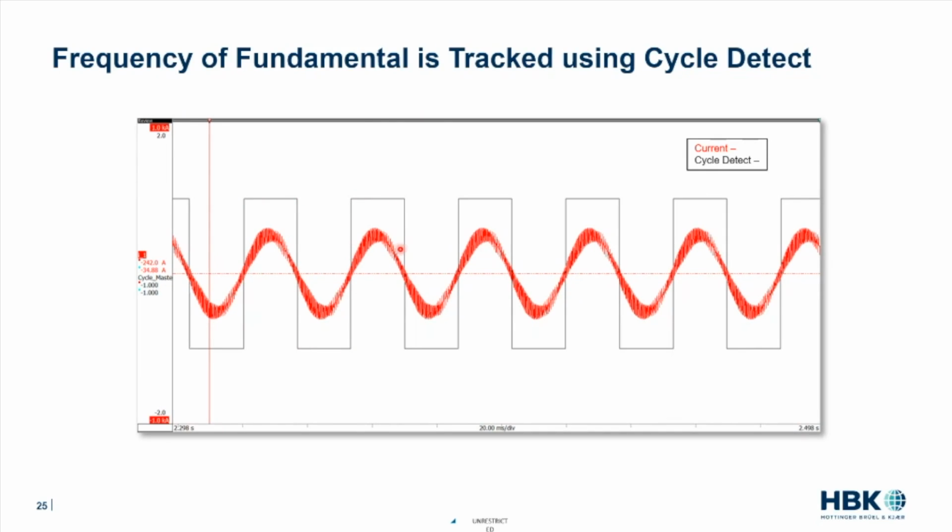So every half cycle, you want to do an analysis. So we take that frequency, and then we do our FFT and we do our harmonic analysis based every half cycle. This allows us to understand, what are my harmonics that are a function of that fundamental frequency. The FFT, I'm looking at everything. I'm looking at things that are not included in my fundamental. I'm looking at weird asynchronous events. Now on the fundamental basis, we're just looking at that third harmonic, that fifth harmonic, that seventh harmonic.